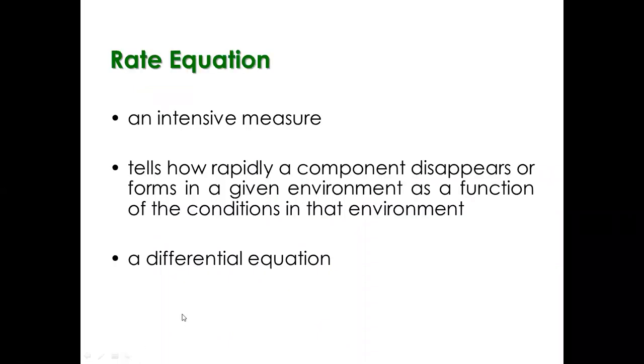So when we speak of the rate equation, which will be appearing in the performance equation for the 3 ideal reactors that we're going to talk about, it's actually an intensive measure. So the rate equation is not dependent on the volume or the amount of the reacting mixture that we are to analyze, and then use the corresponding interpreted data from the experiment in the design of the said reactor. So it's an intensive measure.